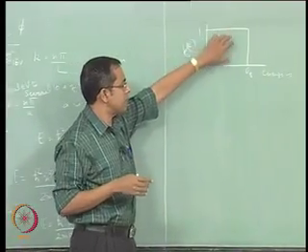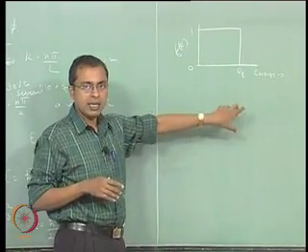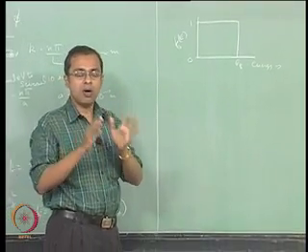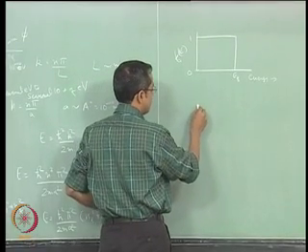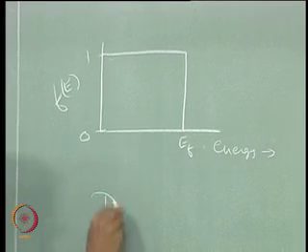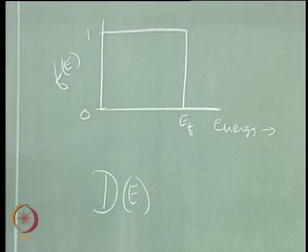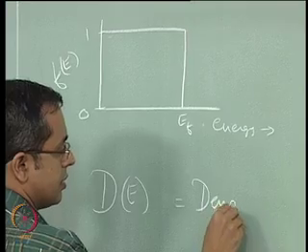So independent of this picture, we have to find out how many energy states are available as a function of energy, and taken together you will get the full picture of the situation, which is how many occupied states are there in the system. So what we are really looking for is a parameter that we represent as d of E, okay, and d of E is called density of allowed states.